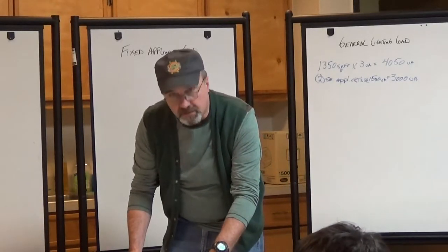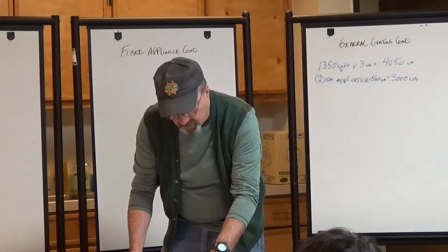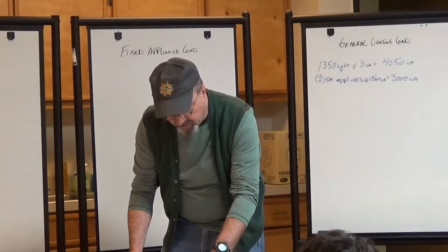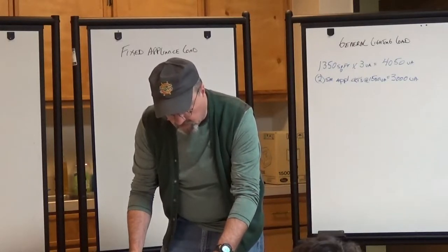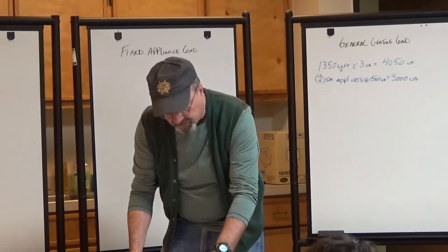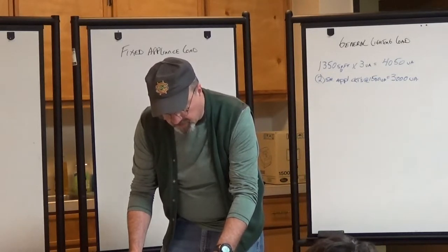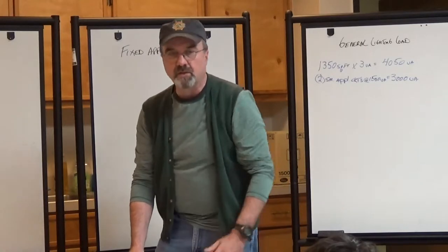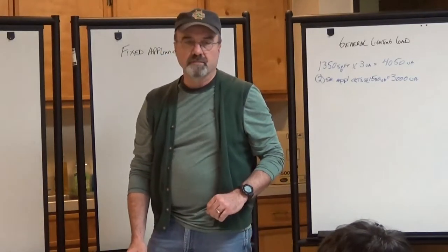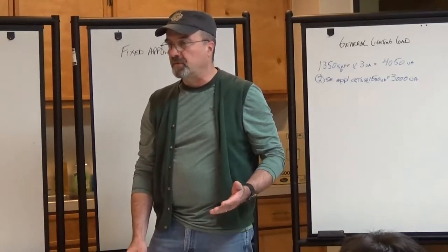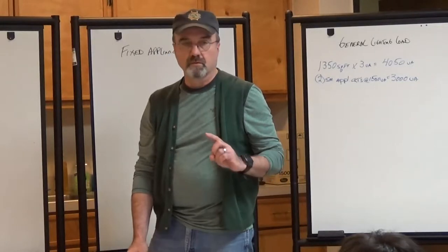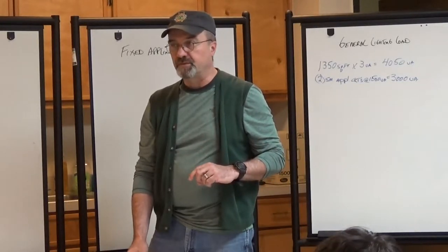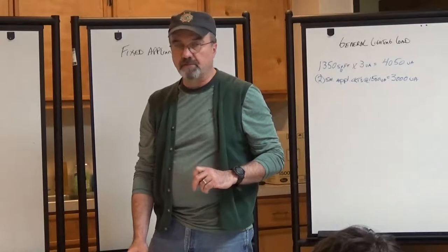It says, in addition to the number of branch circuits required by other parts of the section, at least one additional 20 amp branch circuit shall be provided to supply the laundry receptacle. So in the laundry room, you have your washing machine, and what voltage is that at? 220. Washing machine? 120. 120, right?